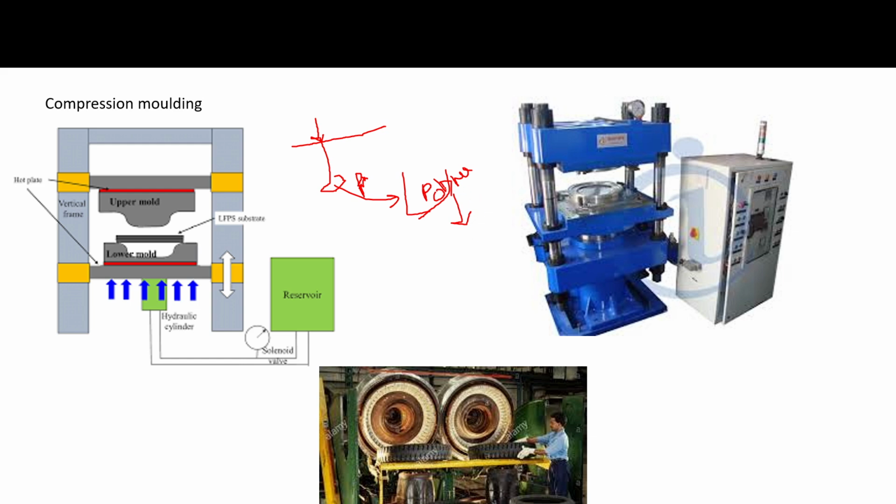To make the polymer useful, to make polymer sheets or polymer materials, we have to process this polymer. So how can we process it? There are two types of polymer: thermoplastic polymers and thermoset polymers. Thermoplastic means that we can easily heat the polymer and it melts. We heat the polymer, melt it, and then give it a particular shape.